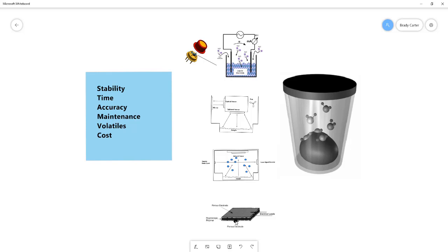That said, the hygroscopic polymer can be unstable when it goes through successive wetting and drying periods. Because when the polymer is subjected to high relative humidity, it absorbs a lot of that water in the polymer, and it continues to drift. And then when you go back down to lower water activities, it tends to read high. So that can affect its stability.